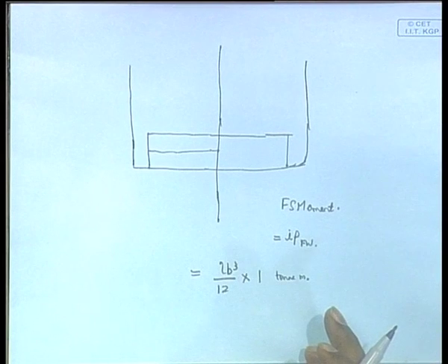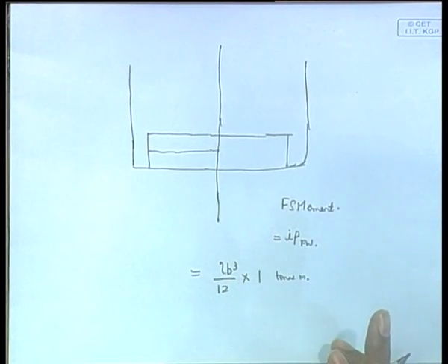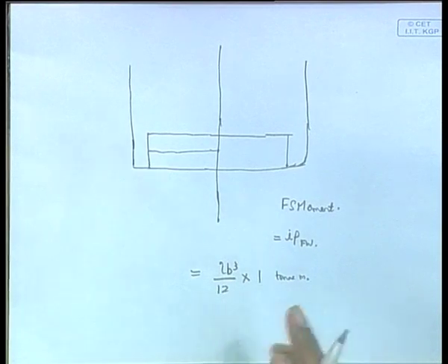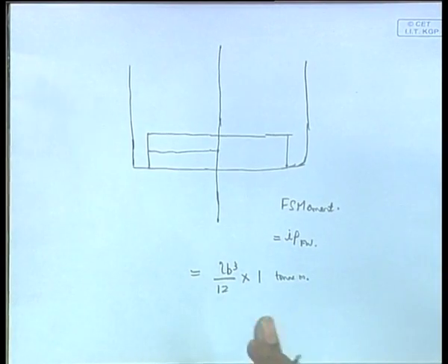Then one important part is the weight. You have to find two things: first KG, and then the moment of that weight, that is the weight multiplied with KG. Then you also have to find the horizontal moment, which is basically the free surface moment, that will come there.